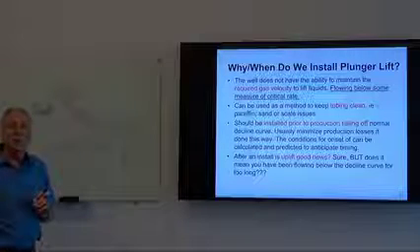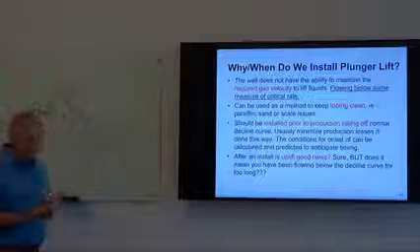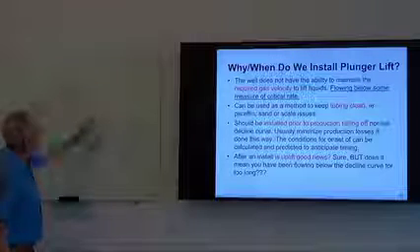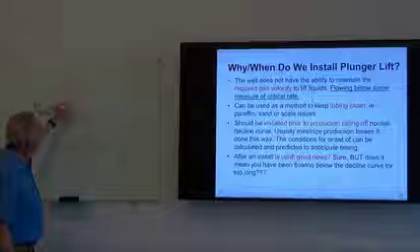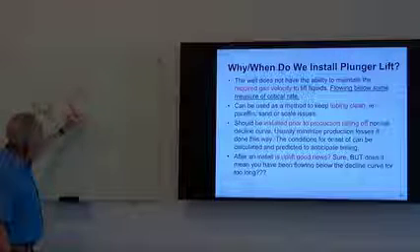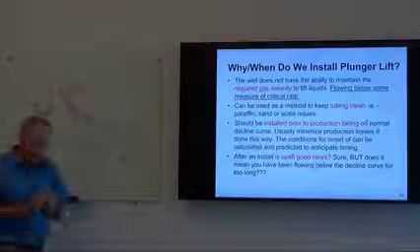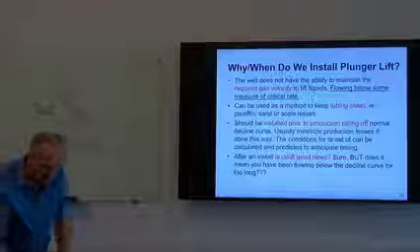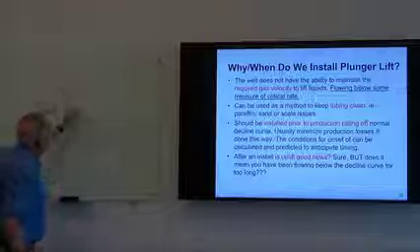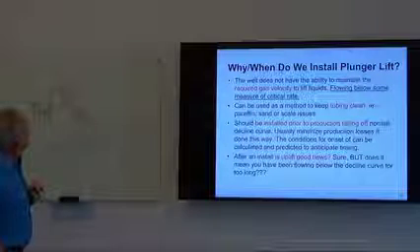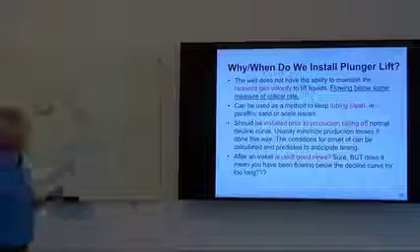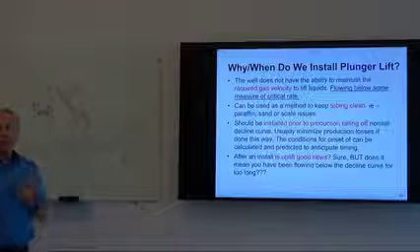And we've had some issues with the well. Due to this liquid loading, we can see accumulated periods below the expected natural decline. And if we sum all of these excursions below the line and add on excursions above the line, which is very small in this case, we can see that over the course of a 1-year period, we have a net loss of production.